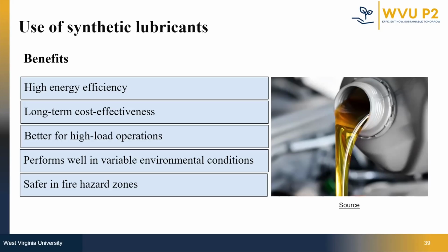We explored the major opportunities for energy saving: repairing leaks, lowering system pressure, using cooler outside air for intake, eliminating inappropriate uses, sizing and locating the storage tank properly, recovering waste heat, and even switching to synthetic lubricants. Each of these strategies may seem small on its own, but together they add up to real efficiency gains, cost savings, and a more sustainable operation.